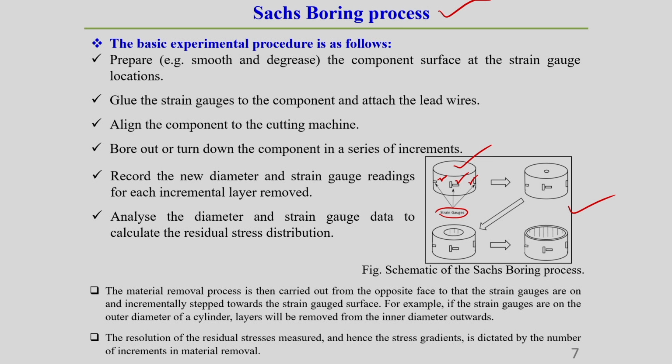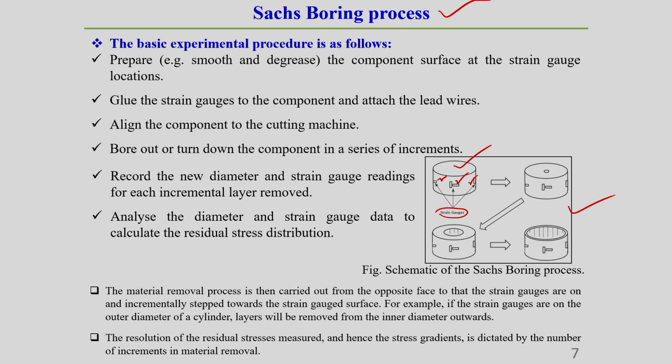That's why I have already told you, whatever strain gauge related measurements there are, the strain gauge should generally be inserted in a laboratory room, because your surface should be neat and clean, as this is a very sensitive component, okay. Once there is a little bit of dust or unclean portion, your reading will be wrong.